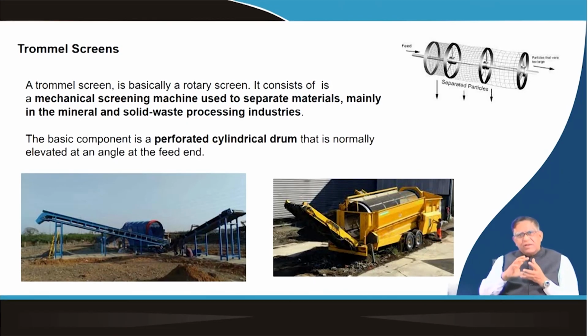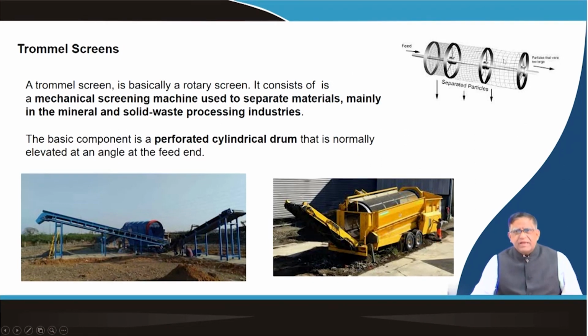Sometimes the coal breaker and the screen can be combined if you use a trommel, as you have seen, that is a cylindrical one in which there are holes. Now, sometimes crushing and screening can be done for friable material, friable minerals or the coal. You feed it from one side and make it rotate, and then the coal or the friable material will go up and then fall down, and when they are falling down, because these are all perforations, they can go through.